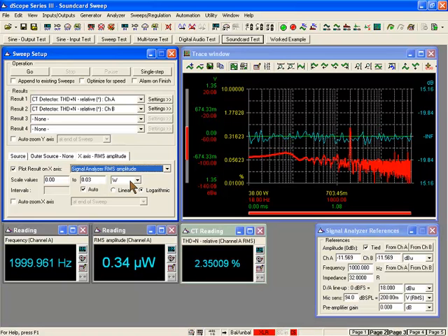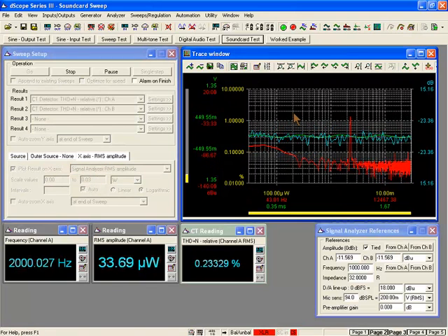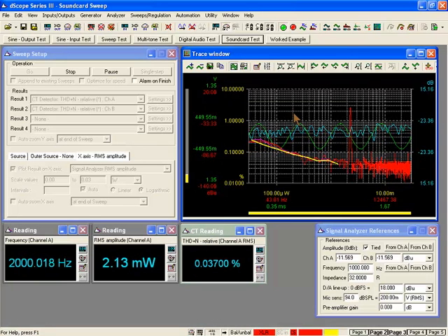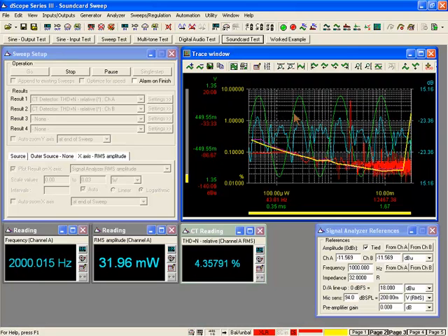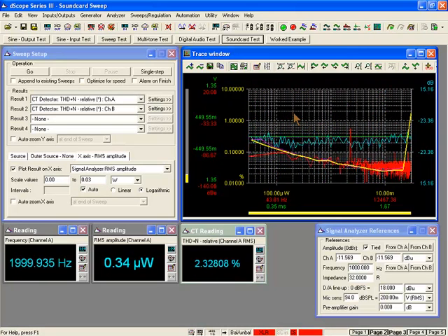Once again, I've slowed the sweep down so that we can actually see it executing live. Let's run the sweep. And remember, no files involved here. The test system is generating the tones and analysing the information that's coming from my laptop headphone output. So the sweep is executing. We're ramping up in signal amplitude, which you can see on the screen there, and we've then just run into clipping as we generated a full-scale 0 dBFS signal at the end of the sweep there.